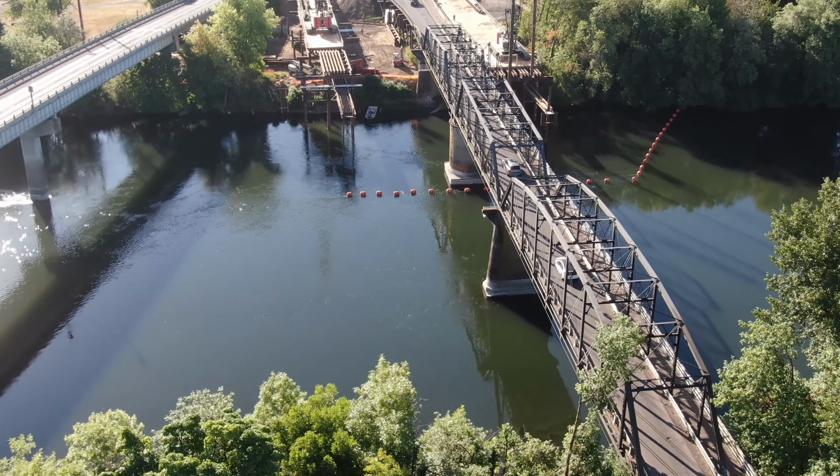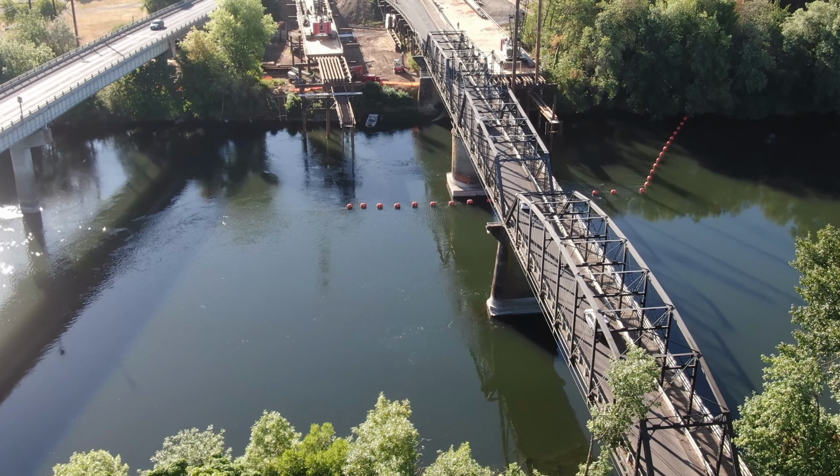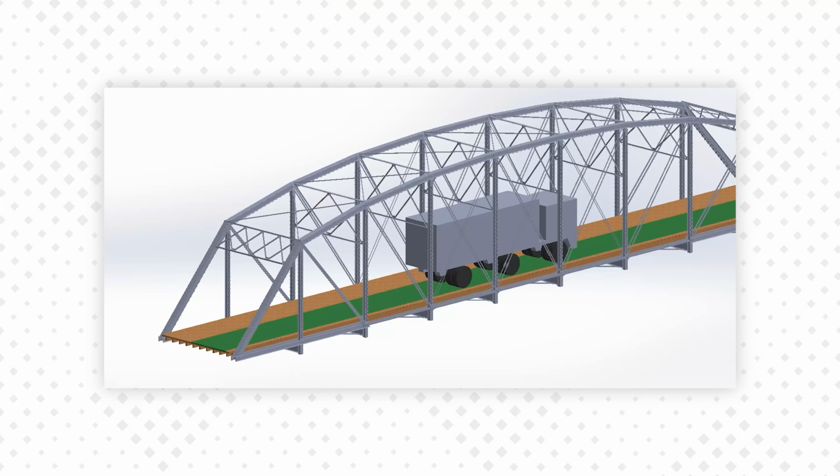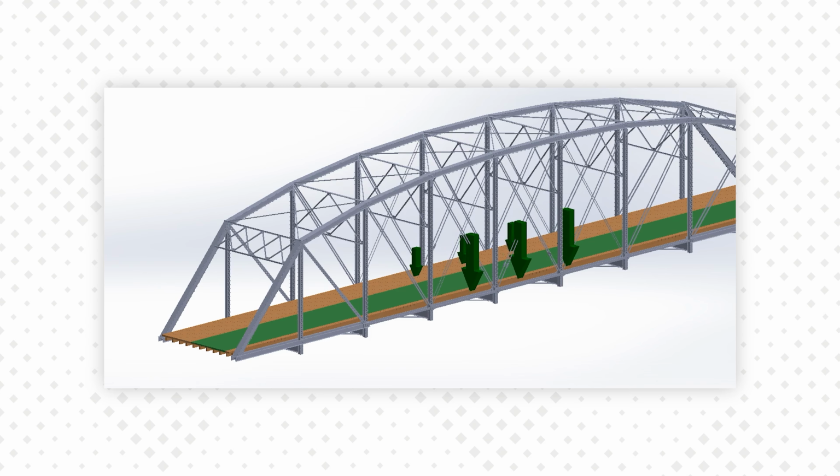Let's look at how vertical loads work their way through the Van Buren truss. Lane loads flow horizontally through the deck, timber beams, and cross steel beams to each panel point. The truck loads move to panel points as well, based on their position on the truss. These loads move up the truss diagonal web members, creating tension forces, and back down the vertical members, creating compression forces.